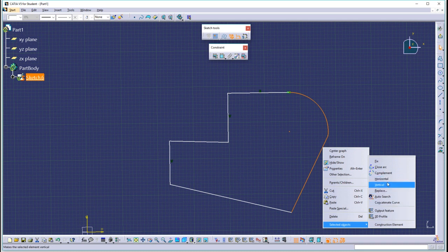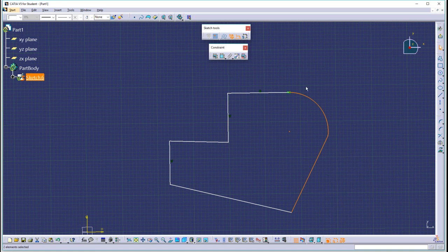In this case, if I wanted to make these two elements tangent, I have to pick one of these buttons. So if I pick this button, it gives me some kind of a length constraint, and I can right click and pick tangency here. This isn't normally what we mean by right click. So we're going to discuss that kind of a right click in just a little bit. Okay. So in order to put an angle between these two, I can't do that with a right click. But what I can do with right clicks is sometimes change some options.